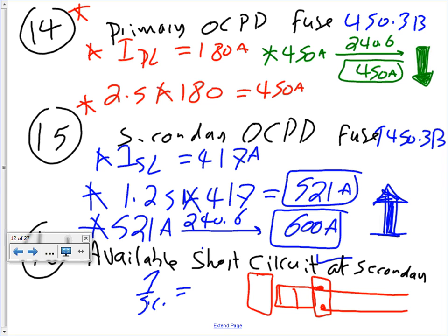From this side, it's tied to the transformer, right? Remember, this is the transformer side. This is where you put your 2 sets. Now, if you're paralleling 3, they will have 3 lugs tied to the same fuse. Make sense? Okay.